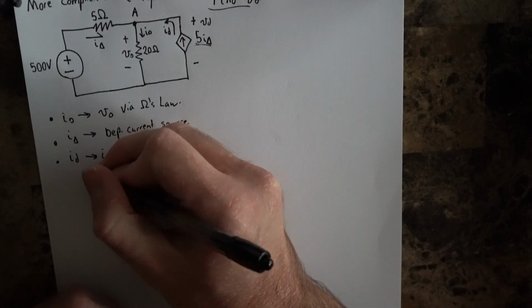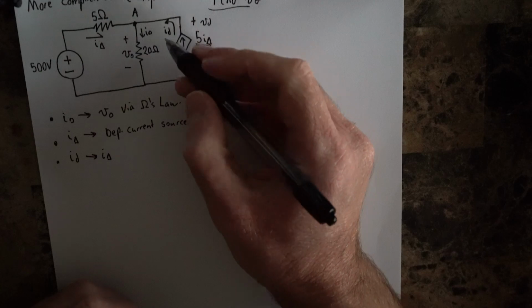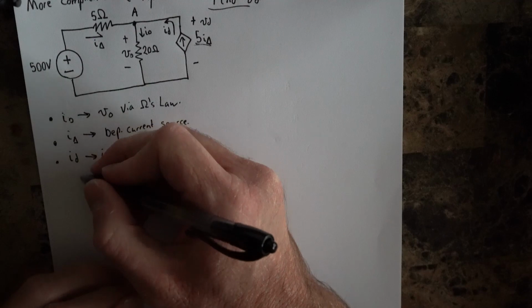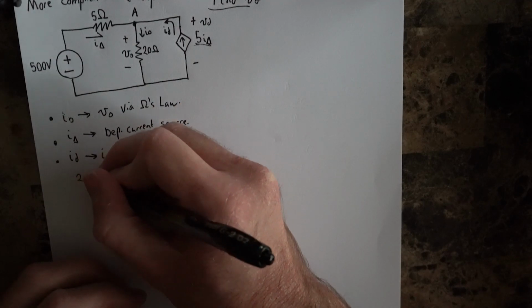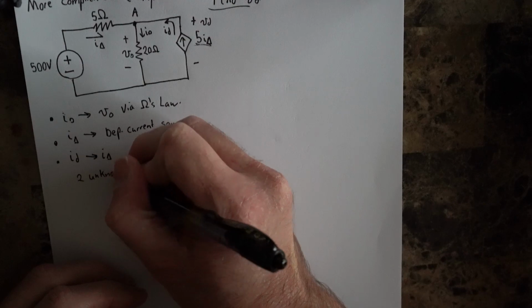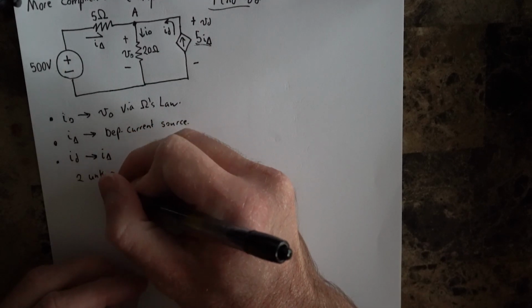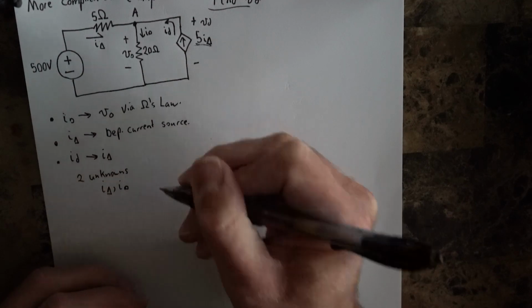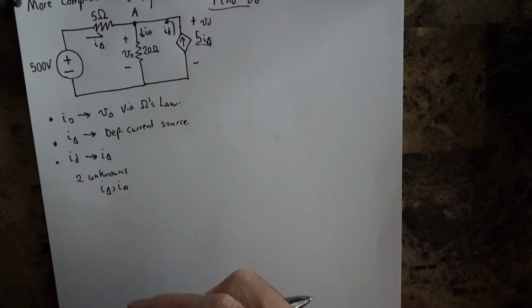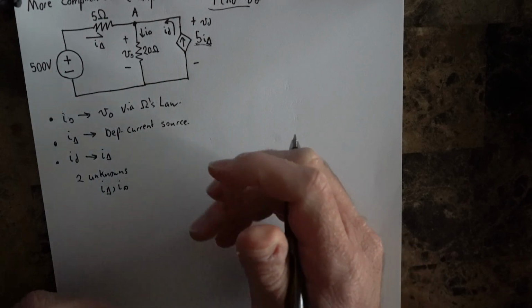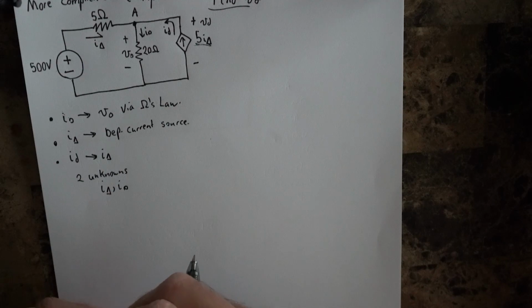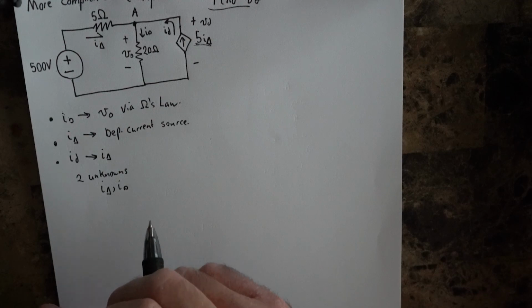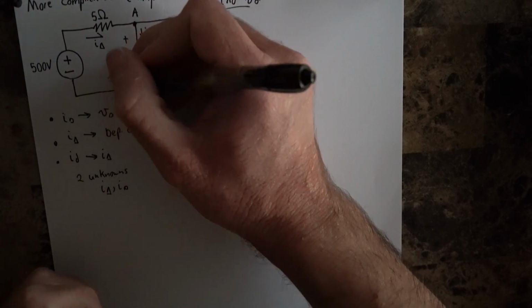So we have two really unknown currents. Well, if you look here, you'll say, oh, Brandon, we've got three, but one of these is a dependent current. So we really only have two unknowns here, being I delta and I naught. So we have a closed loop around that we can solve for right in here.